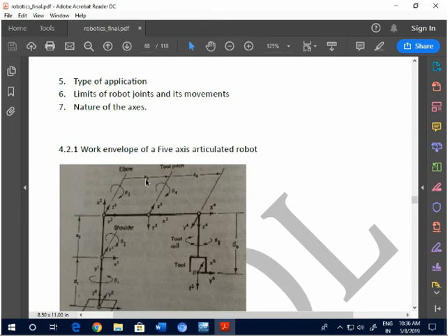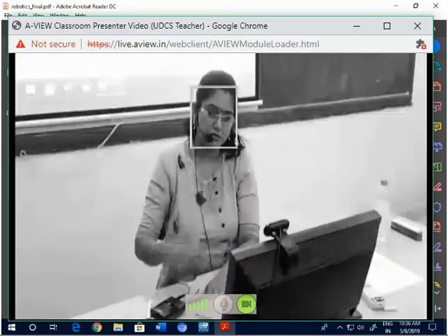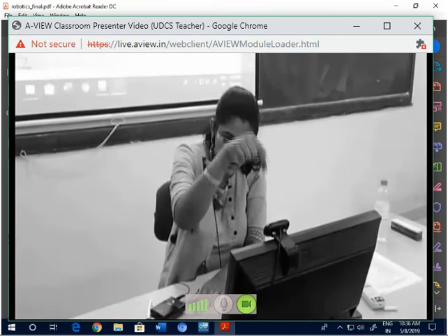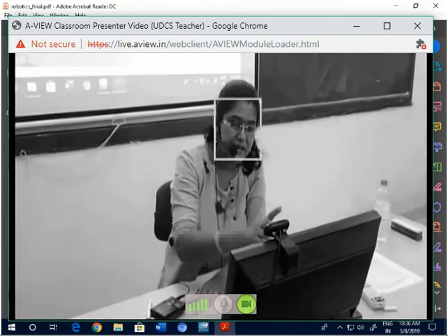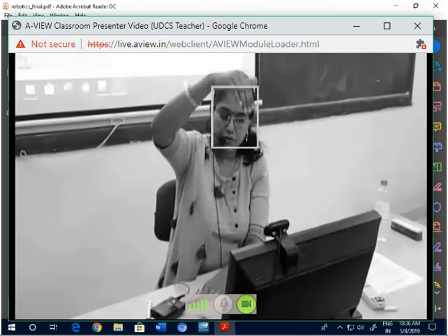Now you have TR, the fifth joint, that is tool roll. This is your fifth joint, and it is again a rotary angle, given by theta 5. The rotation is downwards. Base is vertically upwards. For the tool, the rotation is downwards.